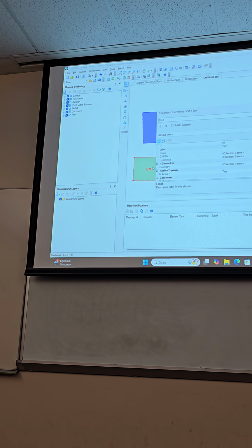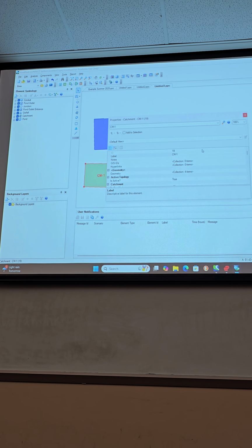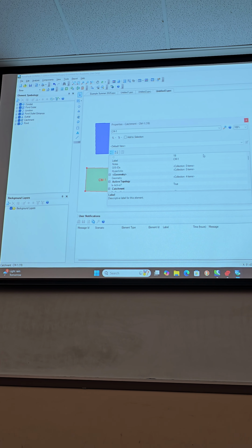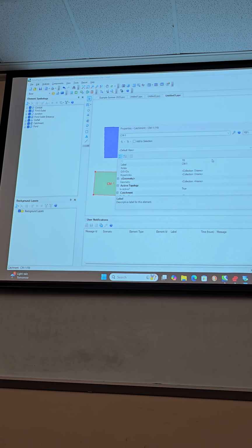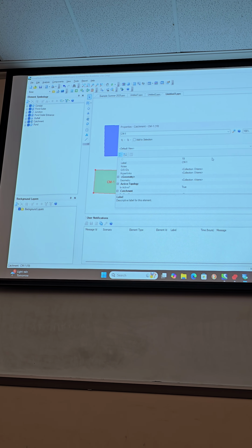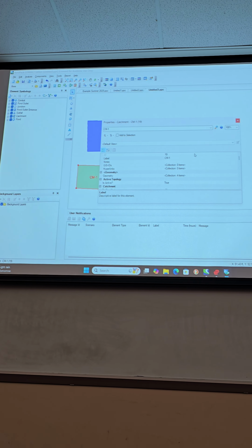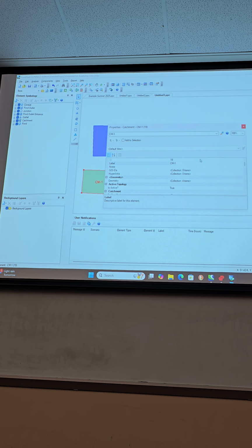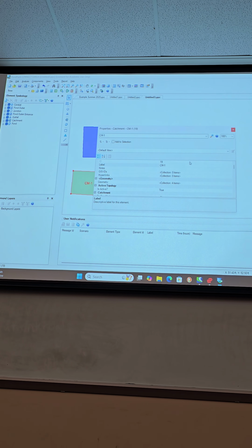catchment area. So if I double click on that, basically, what are the things I need for the catchment area? What pieces of information do I need? What 3 pieces of information do I need? Time of concentration. I need a time of concentration. What else? Velocity? Not velocity. No. CN. We need a curve number. And what else? Area. Area. So we need those 3 things.